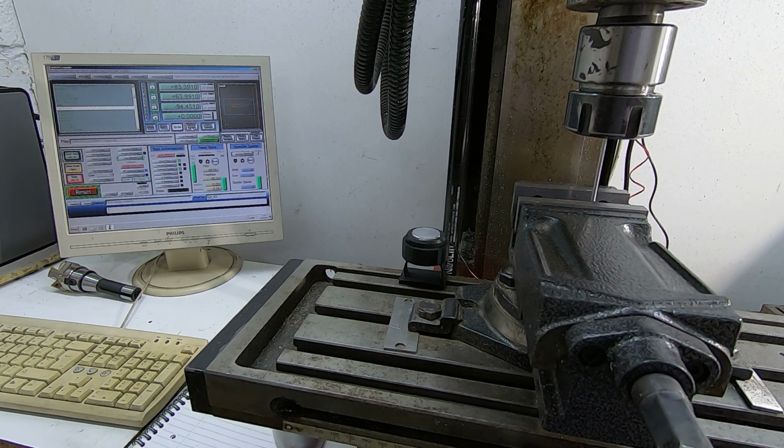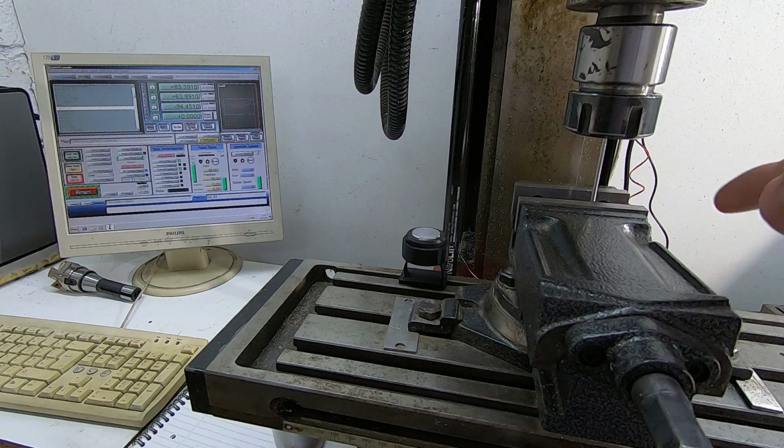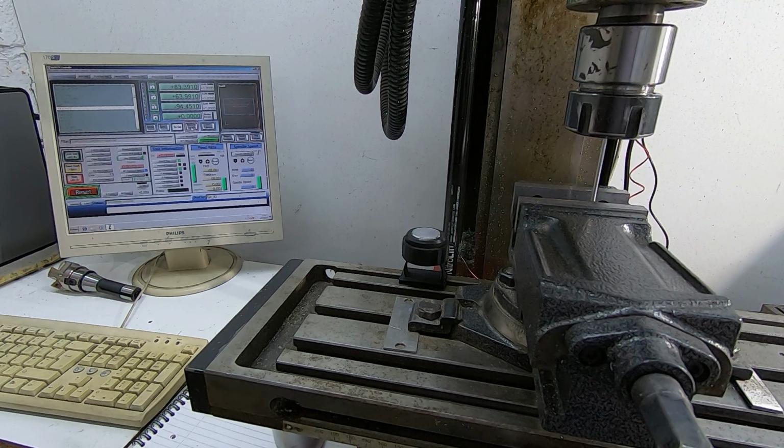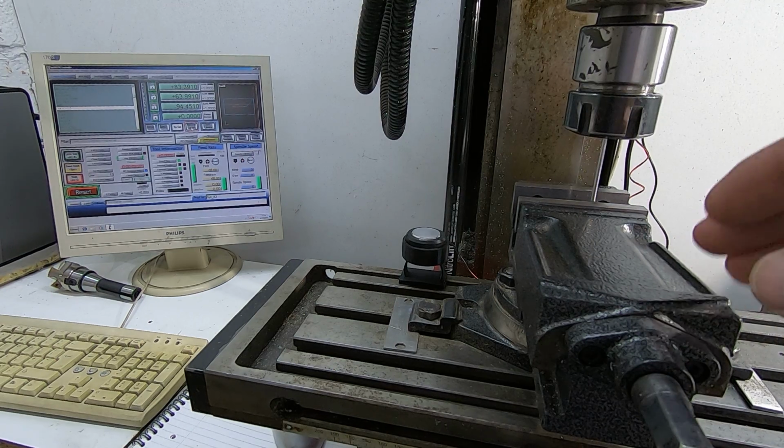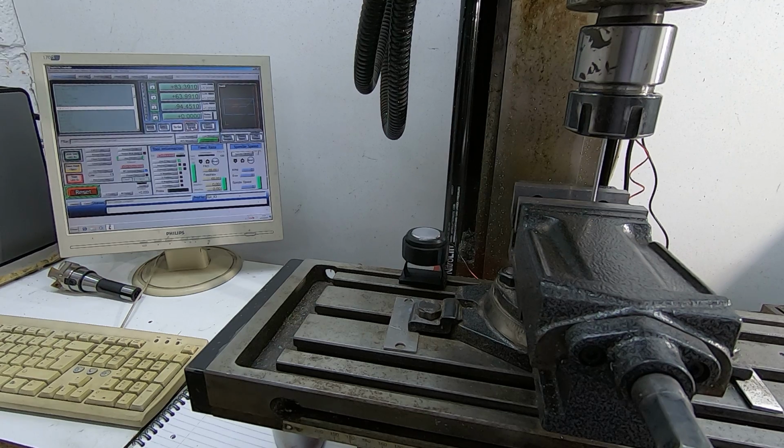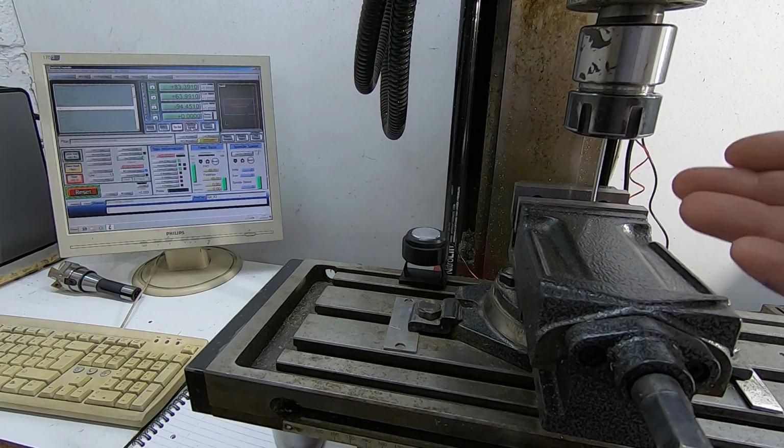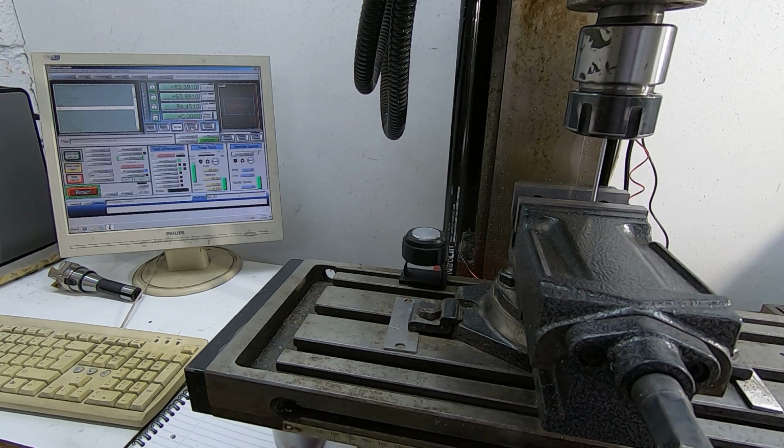But hopefully this has kind of demystified MACH3 a little bit and shown how easy it is to make tool change macros. You could modify it to do whatever you want, of course, but I found this is a particularly good way of changing tools because it means you don't have to mess about pre-measuring tools. You can change the tool as many times as you want within the operation, and while it might seem a bit of a slow process to change the tool, if you've done this much, you'll know that that's a very quick way now of changing the tool, and especially as it gives you a very nice repeatable Z offset position when you do it. Okay, so that's it for this video.